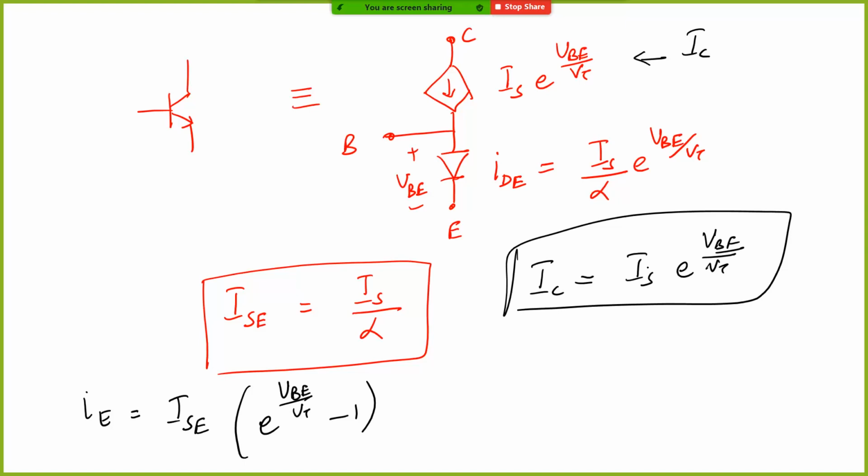Now you cannot say that a BJT is just this. It is a model of a BJT. We started with this structure, and this is what we use. And you will see there is another hybrid pi model which we will study a little later, and which will be used for all your small signal equations. This is one way to model. And there are other things that need to be modeled which are left out. This is for a large signal understanding, and we kind of leave it at that.